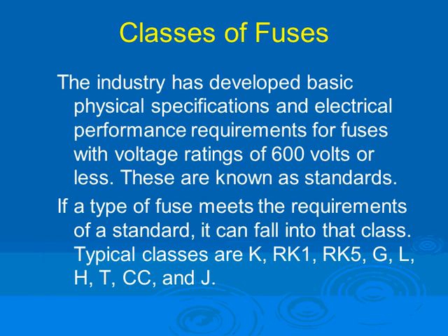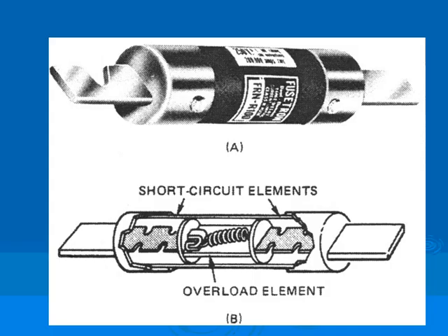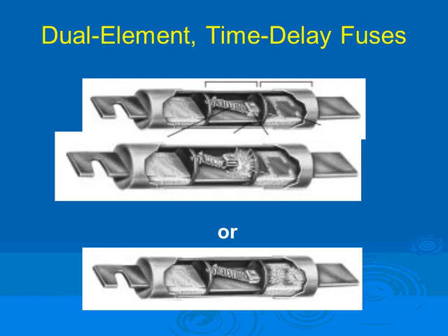Classes of fuses. When it comes to classes of fuses, guys, notoriously famous RK5, current limiting fuses, RK1. So there's all these, and personally, if I encounter fuses in the field and you forget what they're used for, those manufacturers put out a great application guide showing which fuse fits your application better. As in, one set of fuses is great for motors, another set is great in terms of the class, and other fuses, I think, are also great for feeders. So they have really good tables that classify which fuse is rated for which.